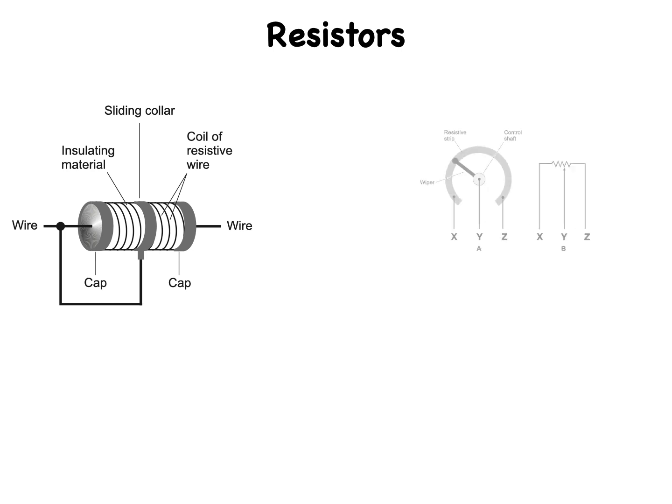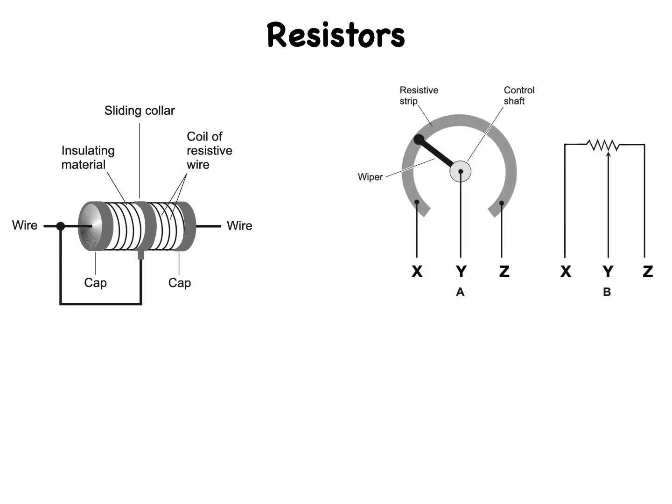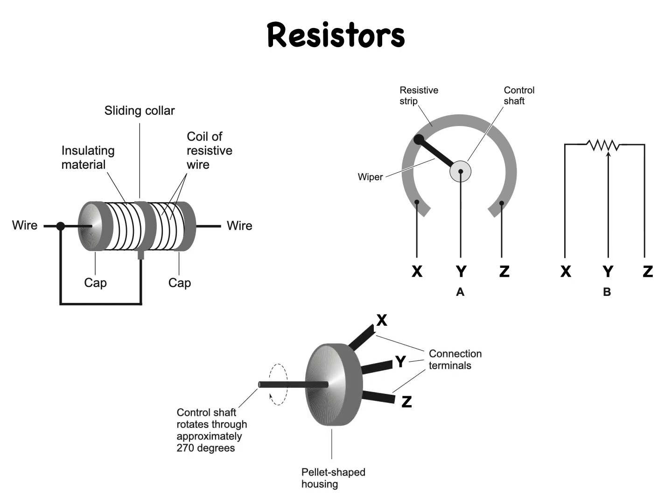This shows a functional drawing of a rotary potentiometer, at A, along with the schematic symbol, at B. The symbol looks like the variable resistor equivalent, but has three discrete contact points. Using the potentiometer control, the portion of the circuit that comes off the arrow lead can be varied in resistance to two circuit points, each connected to the two remaining control leads. Here we see a pictorial drawing of a typical potentiometer.